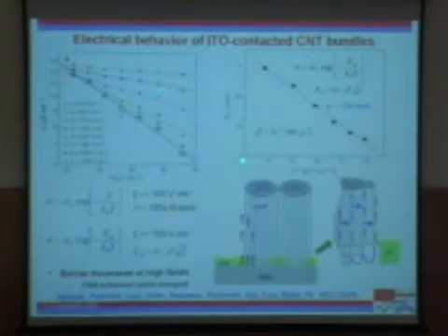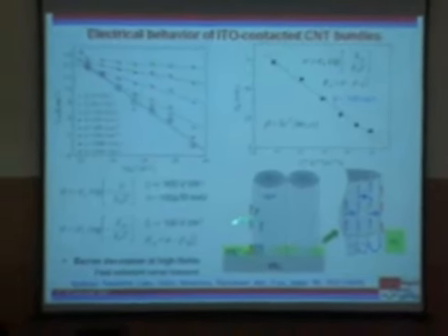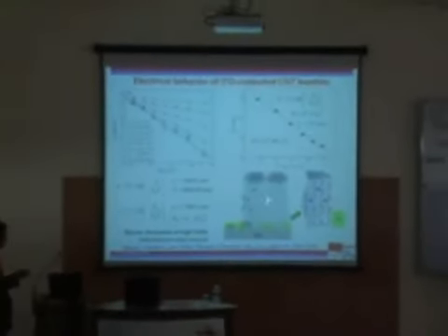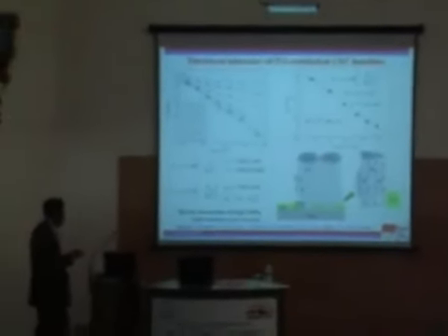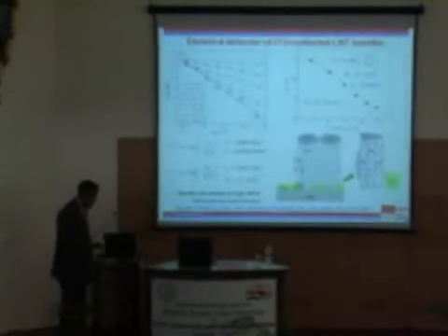Activation energy is decreasing as a function of the electric field in a Poole-Frenkel kind of behavior. What that amounts to is that there are additional pathways for the carriers to go through the carbon nanotubes, and these could be used for interconnects much more efficiently than, for example, a nanotube with just one shell as opposed to multiple shells.